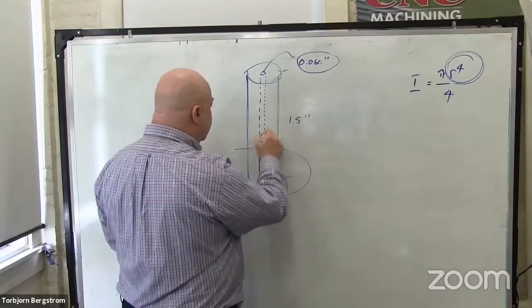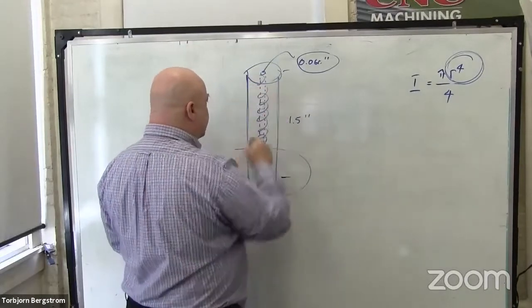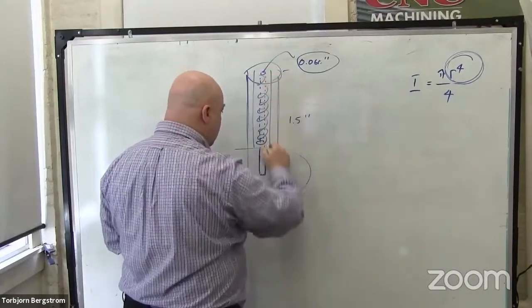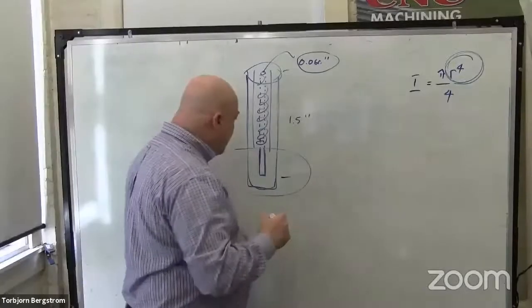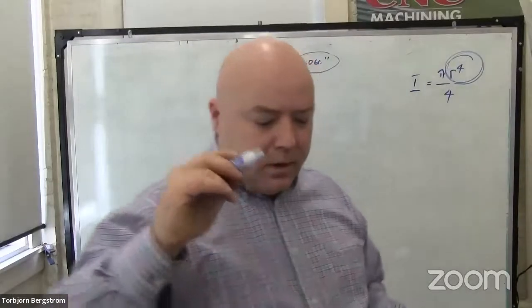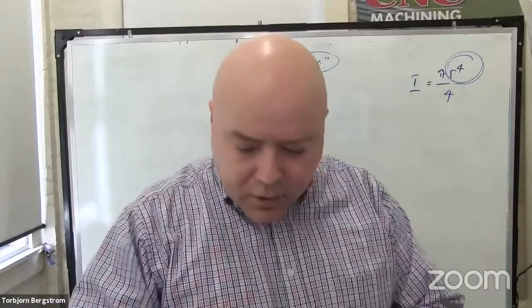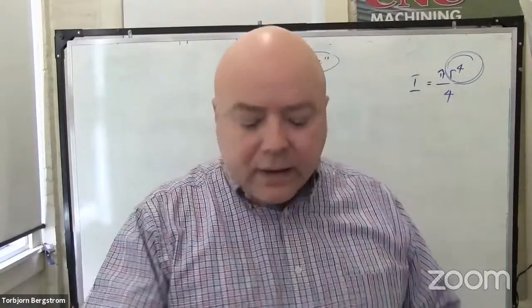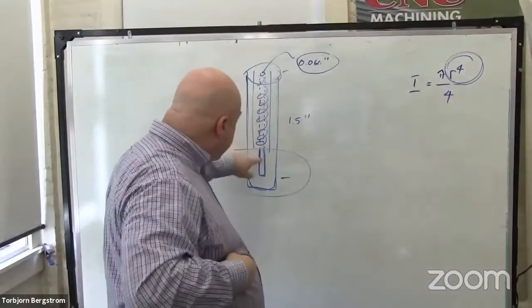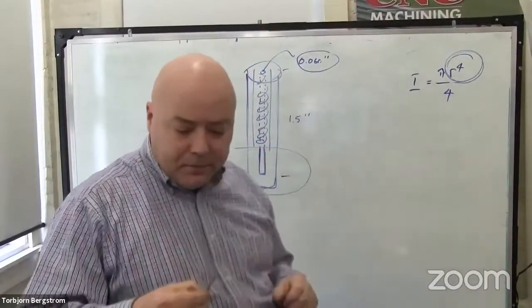They don't need this to be 60 thousandths. We can drill a bigger hole. You're going to break your bit drilling it that long. And then a smaller hole down here. So there are some tricks. You will need a special long, extra long drill bit to make this little bit of it.